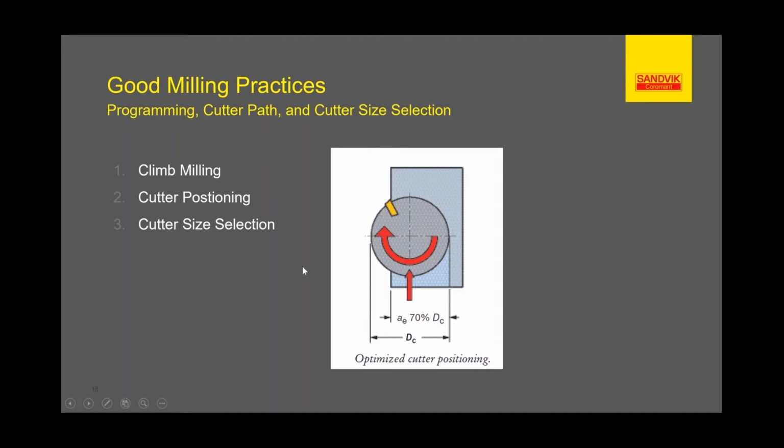Also, you have to consider the rigidity of the part, what kind of fixturing method you have, horsepower and torque at your spindle, what kind of spindle adapter. Is it a 50 taper? Is it an HSK 80? Is it an HSK 63? Whatever, those things factor into how big of a tool you can run. So keep all of that in mind.